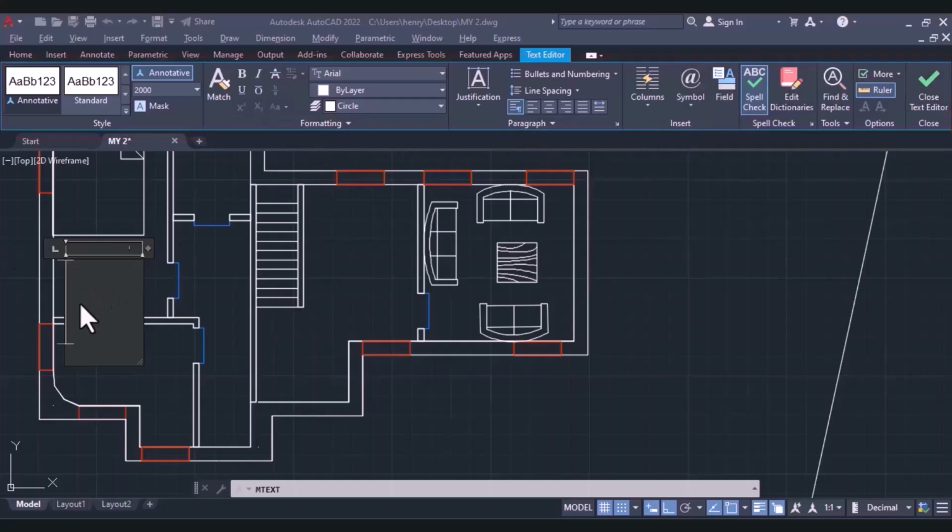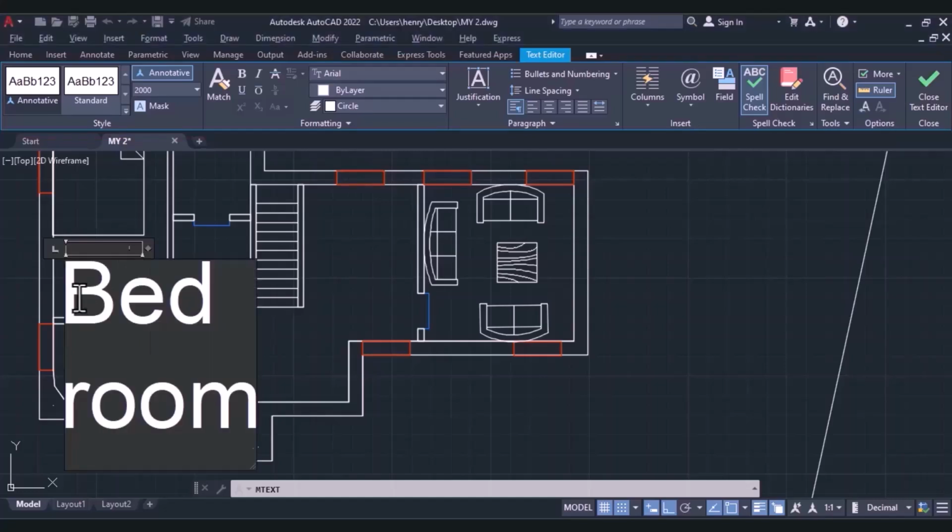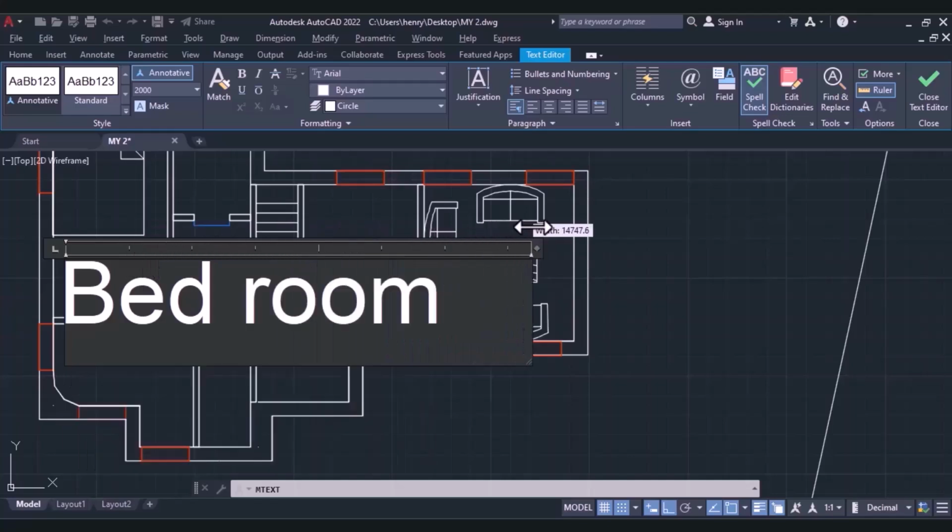So this field over here allows me to type my word. So I'll type bedroom. Notice my text seems very big and falls at 2 rows. So what I will do is I will click on this ruler over here and I will stretch it, okay, and make sure it is in line. Also, the size of the text needs to be reduced. So for me to further modify my text, I will have to select it, because if I go on modifying without that selection, it might not reflect on my text.